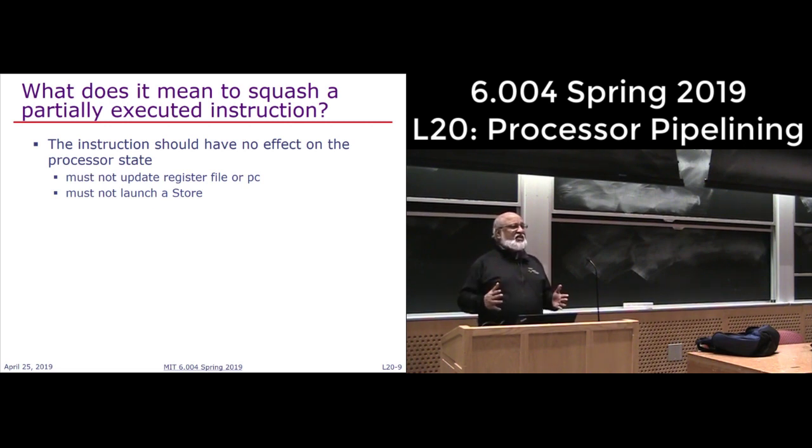And there is no room for error in this. You can say, well, I almost got it right. No, if you updated even a single register which should not have been updated, it's just wrong. Okay, so we have to be very, very careful about that. And for stores, we can't see things directly. My favorite analogy for stores is it's like launching a missile. Once you have sent the store to the storage system, to the memory system, you should assume it will be done sooner or later. You can't say, sorry, I made a mistake, please send it back. Not allowed. So we'll be very careful. We never send any store into the memory system if there is a possibility that that store may be wrong. It may be uncalled for.